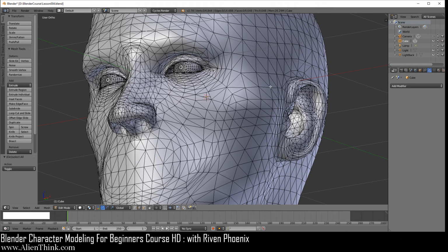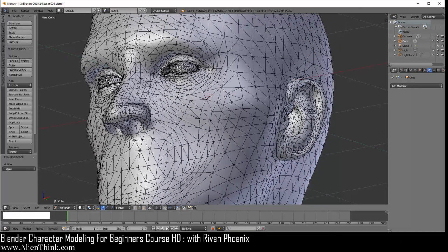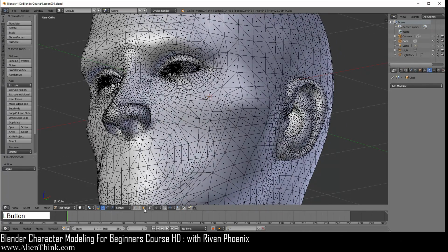It has to do with how 3D modeling works in 3D modeling packages. Because if you come in here, let's say, since we've converted this, if you click on this face, and I do the Alt key and click on this face, you can see that it only selects one face. Before, when we had quads and pressed the Alt key, we were actually able to select a whole bunch of quads going all the way down.